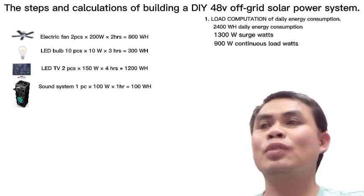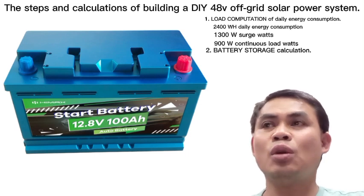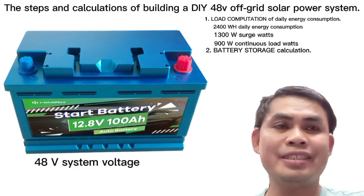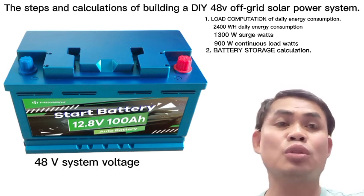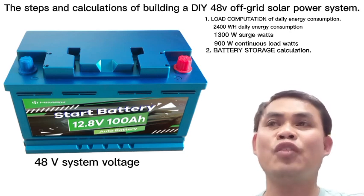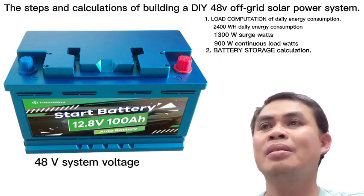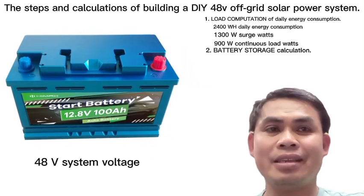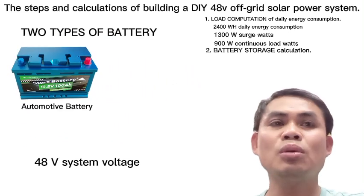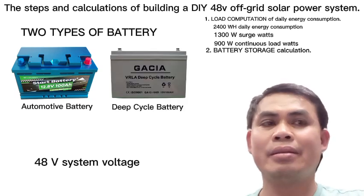This is step 2, battery storage calculation. First, we decide on a 48 volts solar voltage system, because we also have 12 volts and 24 volts, but we decide on a 48 volts solar power system. Then on the battery selection, we have these two types, the automotive battery and the deep cycle battery.